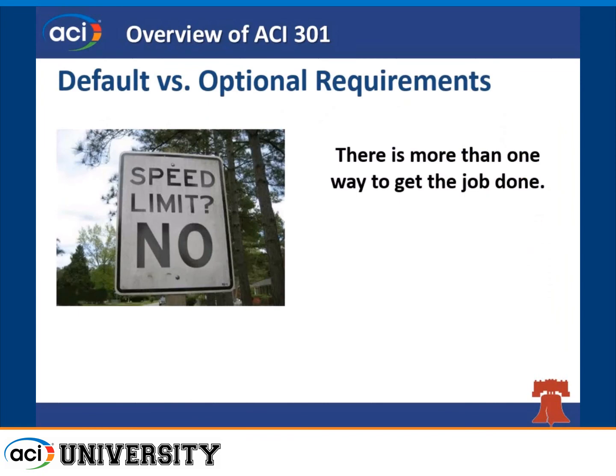I know the gentleman had a question on drilled piers. So to answer your question, I would say that you do have the opportunity to reference 301. You probably would want to look closely at what's in sections 1 through 5 and make sure it covers everything that you want for general concrete. But then your provisions within the drilled pier document would have to go beyond it. So you can look at the way that we've done our special applications. And it says basically follow sections 1 through 5, except for where it's written here. And you add on all the other special criteria that you have for that type of concrete. Does that answer your question? If you ran away after the period.